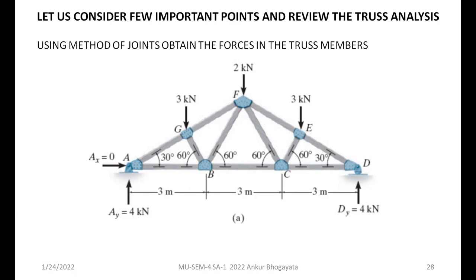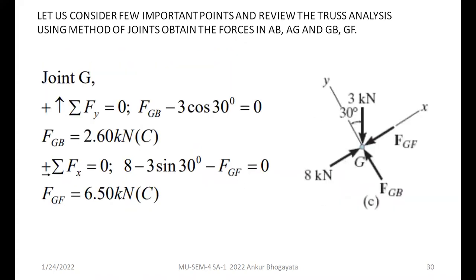So the method of joints in that way is very powerful, giving you the quick solutions, right? Because only two conditions are required to be applied, sigma V and sigma H. There is no role of sigma M in the method of joints largely. But in case of the method of sections, you must refer to the third condition also. So at joint G, this is the answer.